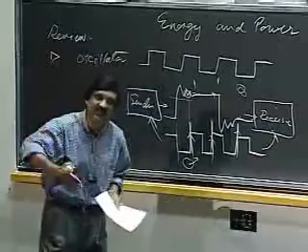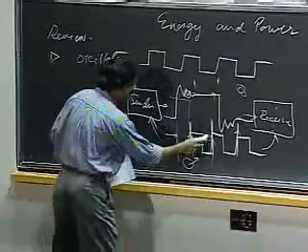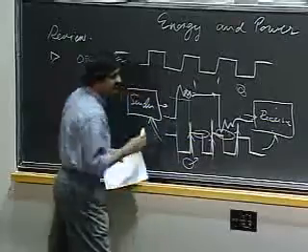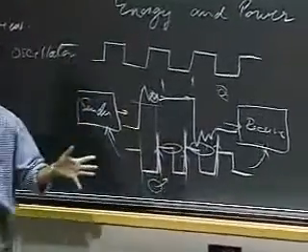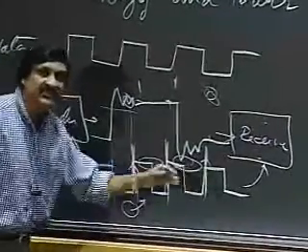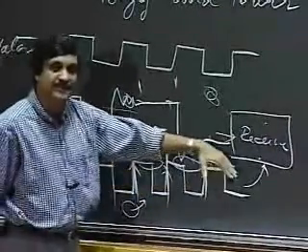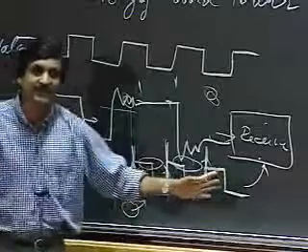That tends to discretize time, which means that I really don't care what happens to signals in this time, as long as on the rising edge of the clock, I get the right value. This concept is called discretizing time, and a clock lets you do that.